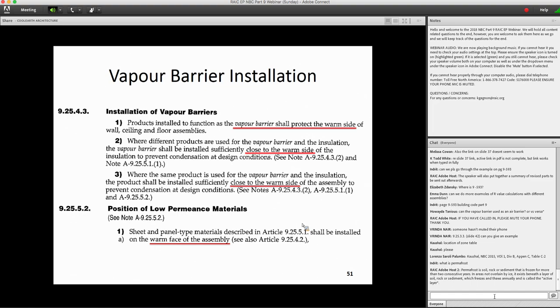And if you have some condensation or some leaks within the wall, you want those leaks or that condensation to dry outside in the summer. So this is where the code tells you to put the low permeance materials inside on the warm side, and this is the building science part, not the code: leave the high permeance components, the ones that have good vapor diffusion, to the outside.